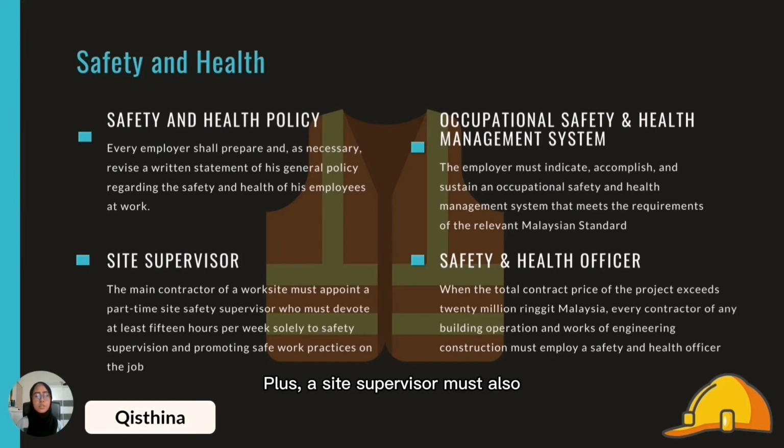Plus, a site supervisor must also be in a construction project. The main contractor of a work site must appoint a part-time site safety supervisor who must devote at least 15 hours per week solely to safety supervision and promoting safe work practices on the job.